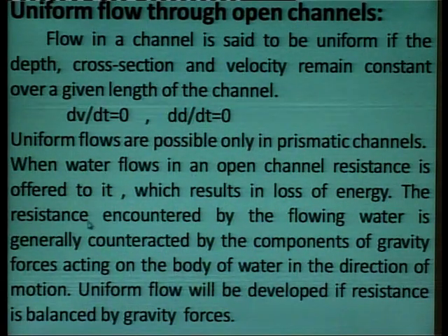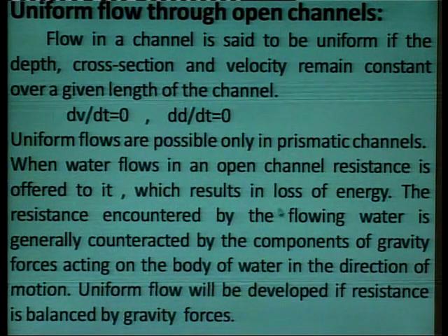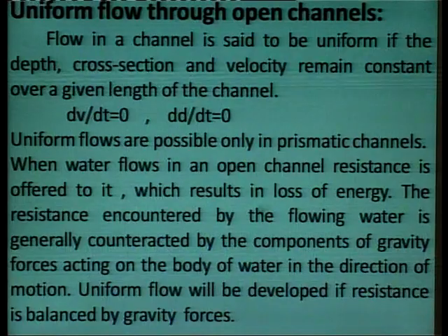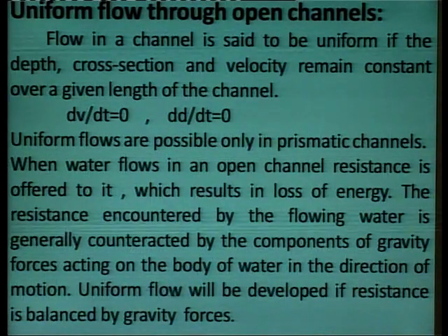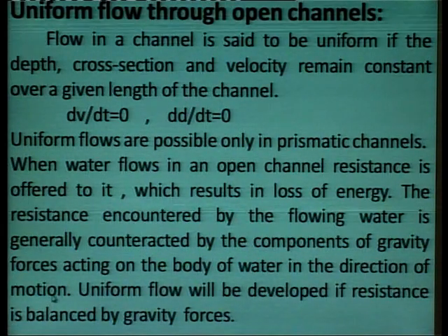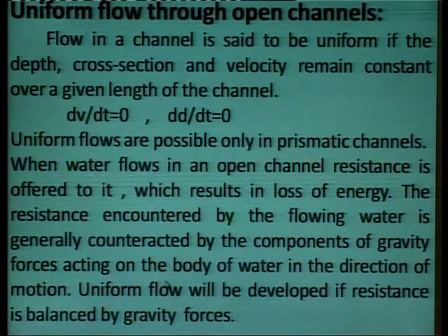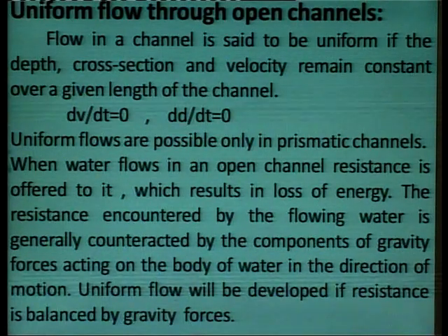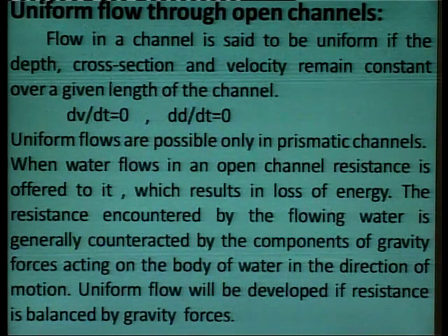The resistance encountered by the flow of water is generally counteracted by the component of the force of gravity acting on the body of water in the direction of motion. As we have already discussed, uniform flow will be developed if the resistance is balanced by the gravity forces.